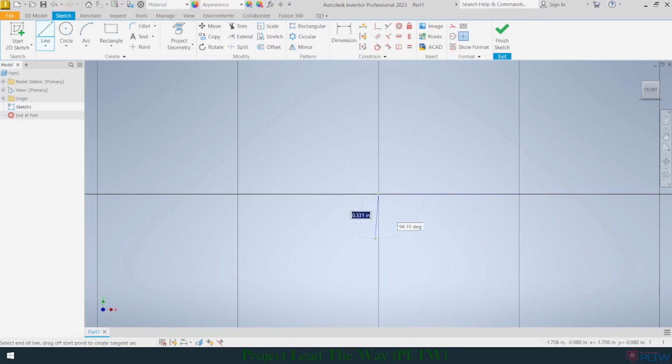So what we want to do is make sure that the line is being pulled down. I'm going to type in DIA, and then I'm going to hit the slash mark, or divided by 4, and I'm just going to press enter. When I do that, you're going to notice that there is a function option. I'm going to hit escape real quick to get out of the tool, but this is a function option, and it makes the dimension look like it's pulling from something. That just means that it's pulling from the parameters that we've already established for this file.